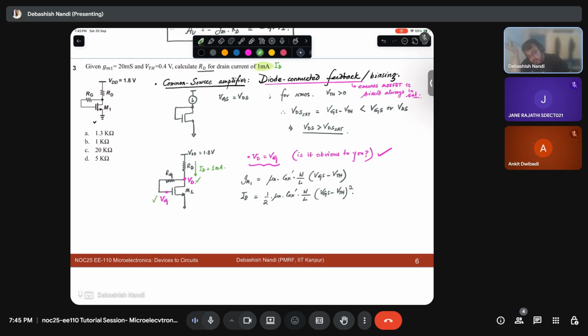So in this case, what I'll do? I'll do GM1 by ID. Again, I'll have the same thing, 2 over (VGS minus VTH). So I know my GM, I know ID, I know VTH, so I can find my VGS.